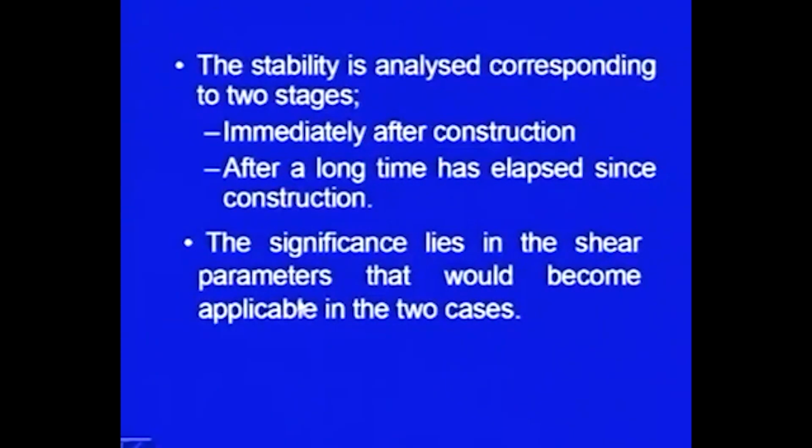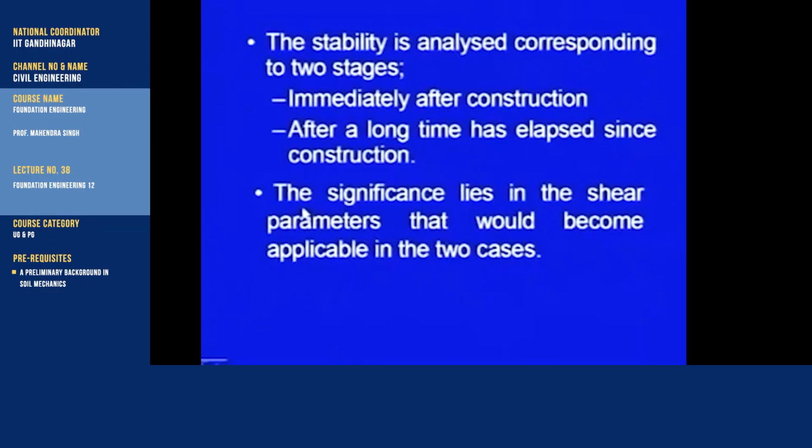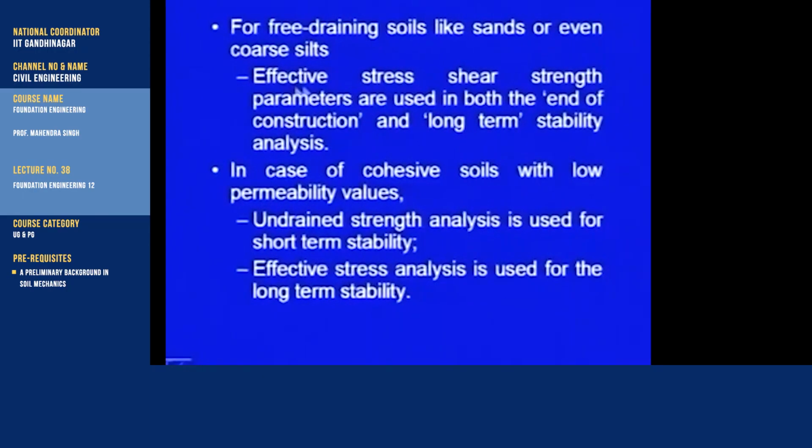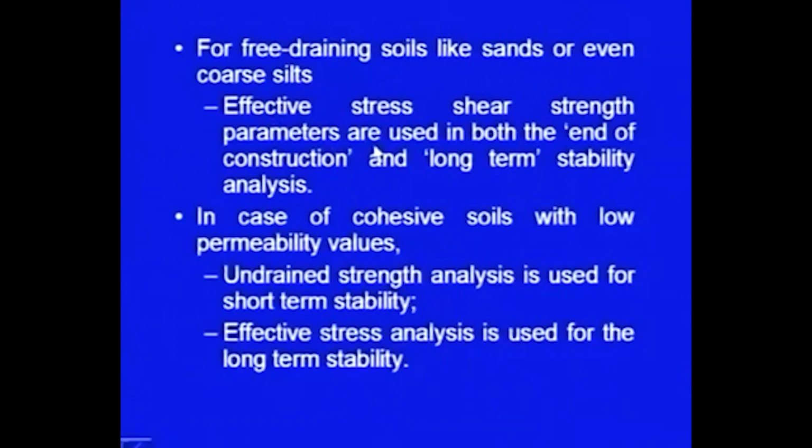So, we consider both these situations, and the significance lies in the shear strength parameters that would become applicable in these two cases. You have to decide which kind of shear strength parameters you have to use for this analysis. For free draining soils like sands or even coarse silts, effective stress shear strength parameters are used in both the end of construction and long term stability analysis.